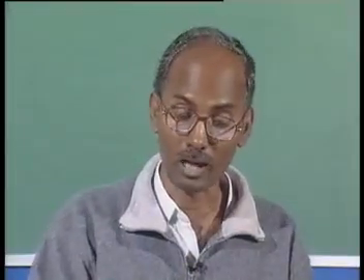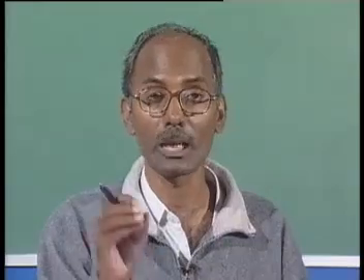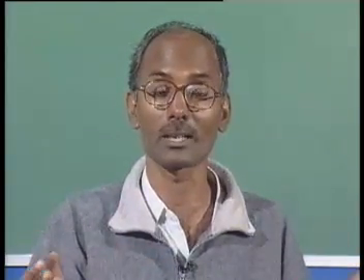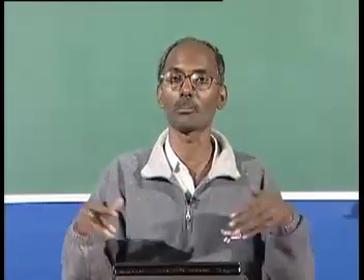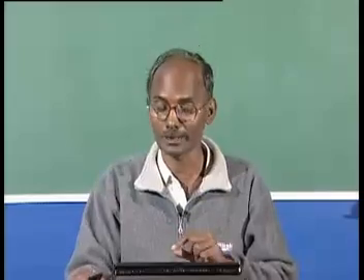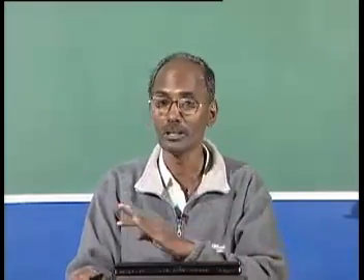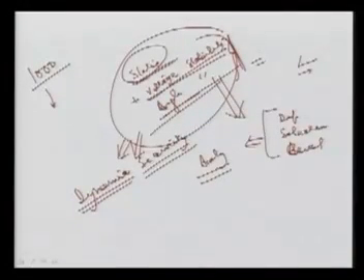Now you are going to include the contingencies with their critical clearing time, which types of faults, and how many faults there can be on one line. So the number of cases is enormous, and then we go for contingency selection and analysis again. For dynamic security, it is a very, very hard task. So we require very fast calculation of these, so that we can go for dynamic security analysis or assessment as well.